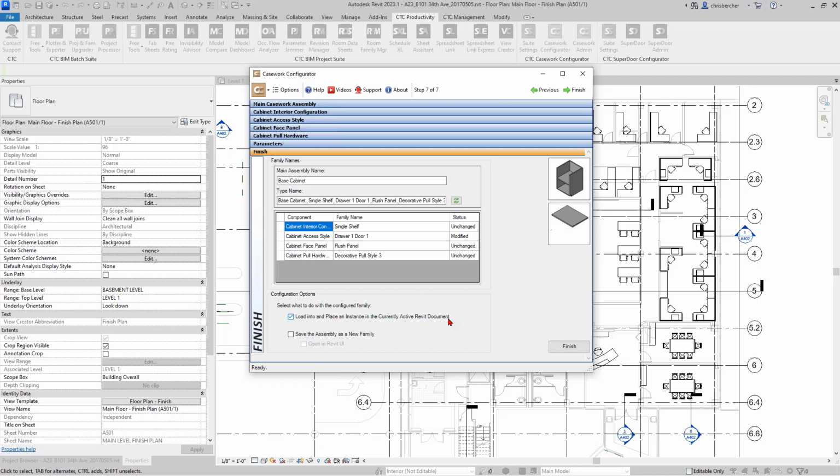You do a lot of residential design. We got very similar base cabinets that we use in wall cabinets. Or you're doing healthcare, we're using the same cabinets there. Or multifamily housing, right? We're repeating the design frequently. There's not a whole lot of variation there potentially. So you could just make the configurations, save them out, and just reuse them over and over and over again.